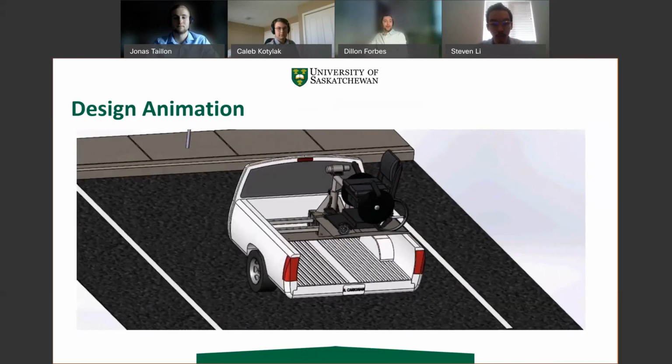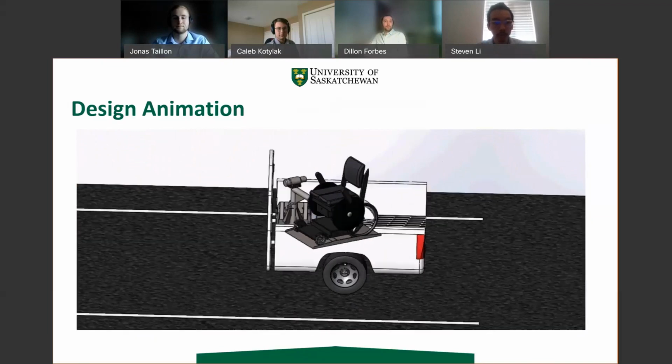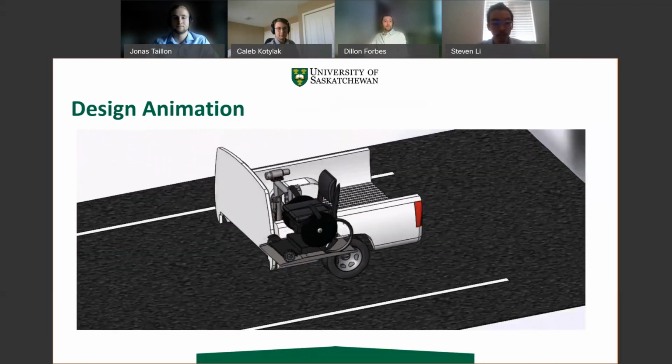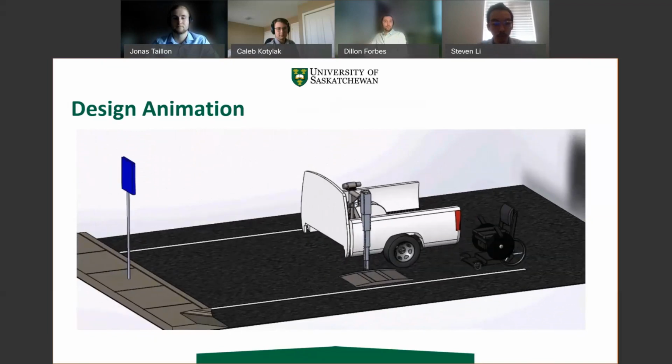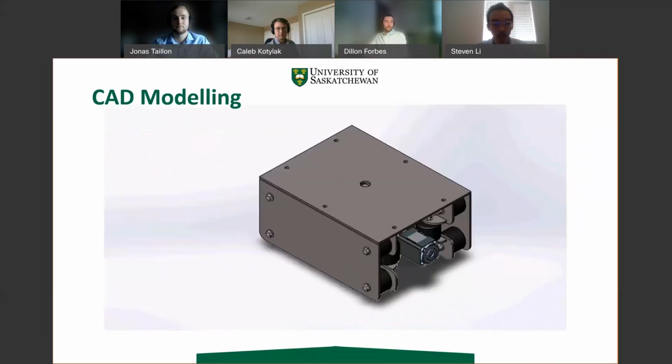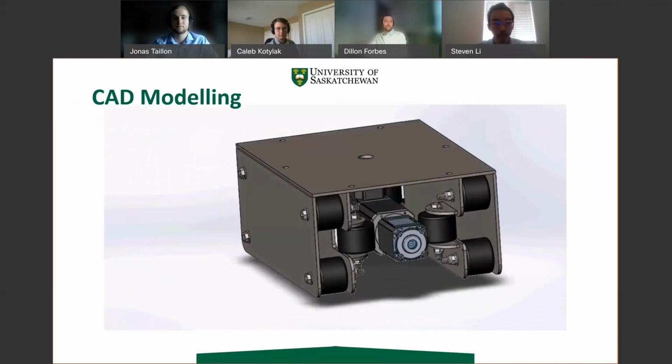Regarding the design safety factor, we consulted the government of Saskatchewan vehicle standard and inspection agencies. Using this information, and trying to minimize the overall weight, we ensured all components met a minimum design safety factor of 2. Regarding the CAD modeling, as no prototype was built, all assemblies were modeled with high attention to detail.